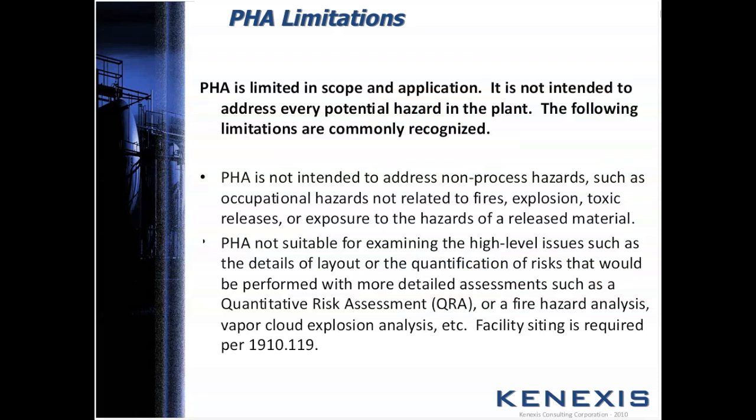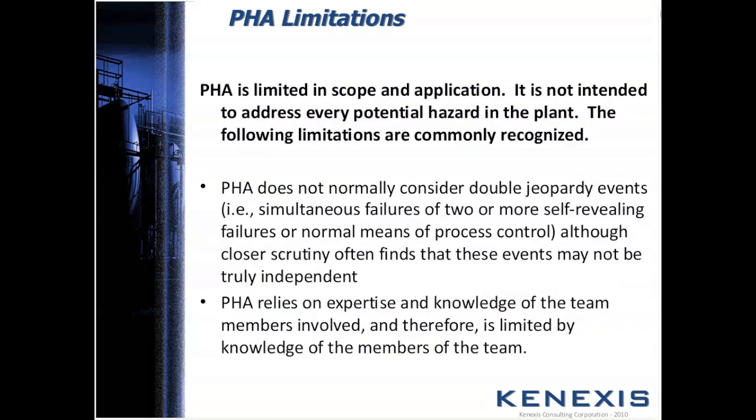They're not intended to address non-process hazards and higher level issues that require a QRA, such as dispersion gas cloud analysis or other kind of things. That should be done in a different study. Okay? Not necessarily done in a HAZOP. HAZOP doesn't consider double jeopardy events.